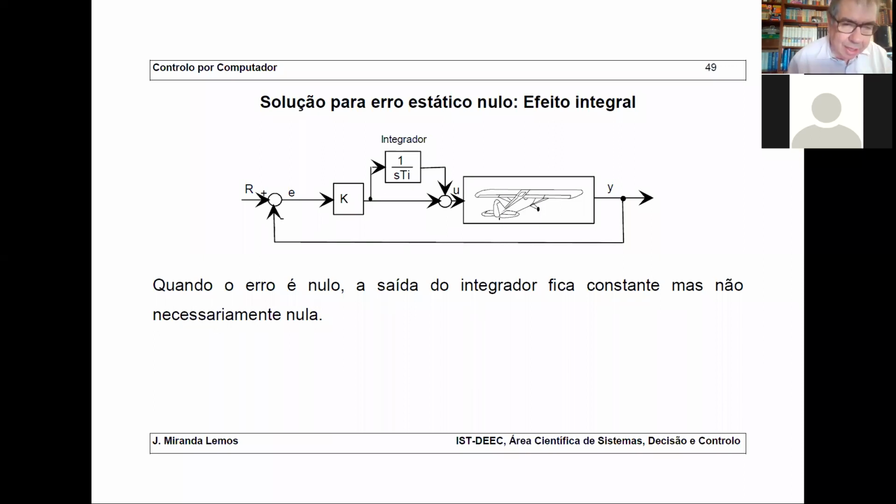Okay, I will give you a hand. Actually, we can think of two things. Well, one thing has to do with performance. If you add an integral, the response of the integrator is slow because it goes on integrating the error, so it needs some time to reach the correct point. So if you just have the integrator, the response would be slow.